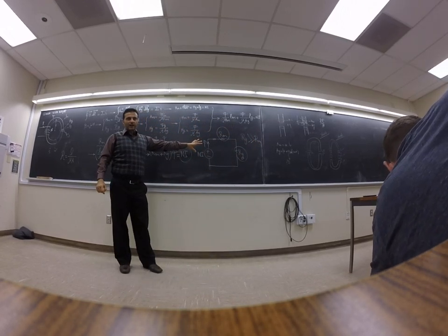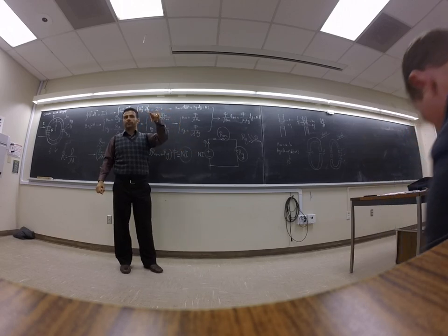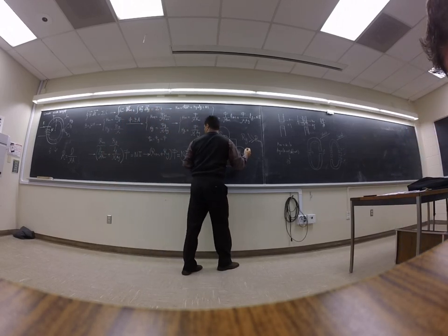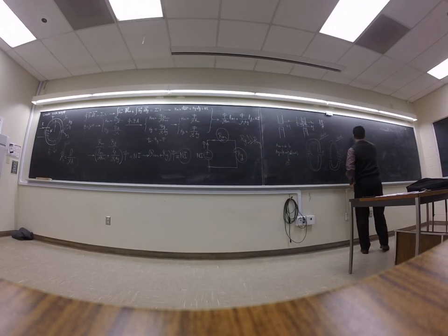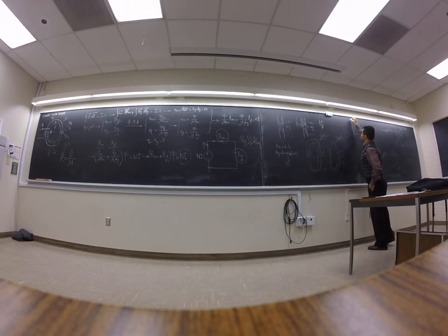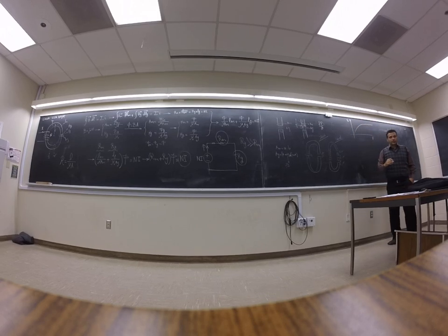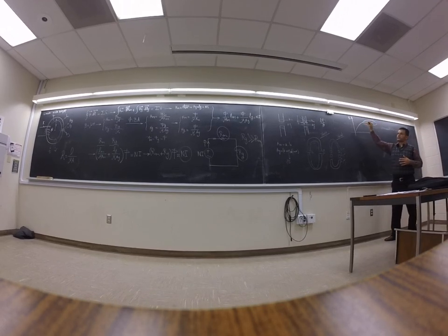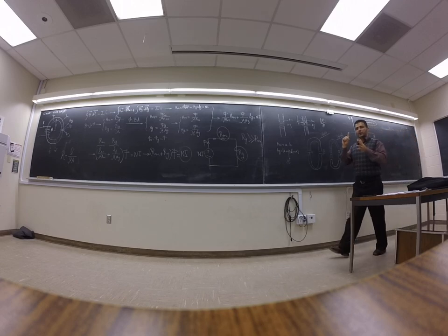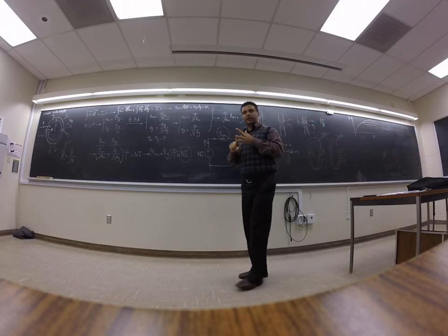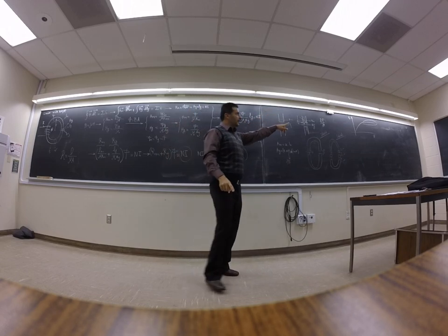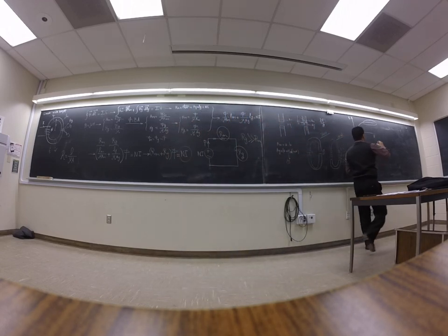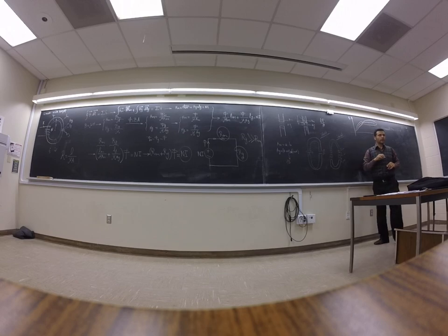So if you go back to the BH curve, I talked about the BH curve. Remember, the BH curve is not like this. This is the B versus H, right? So you don't want to come here, because saturation is going to cause lots of problems: heating, not working linearly, all those kinds of things. To prevent getting there, you have to stay here. You have to control your B.